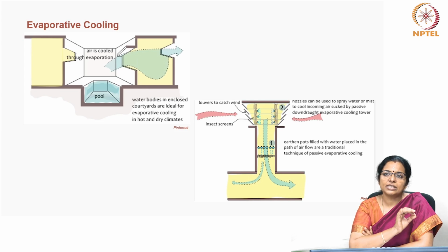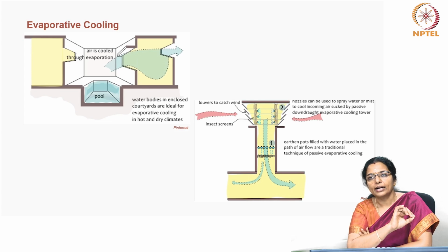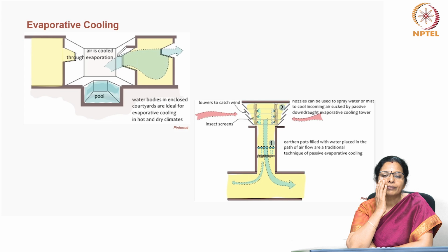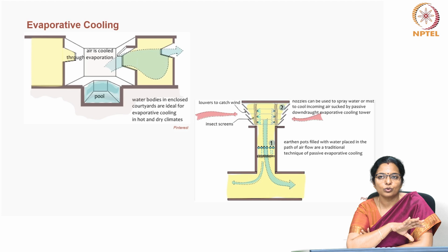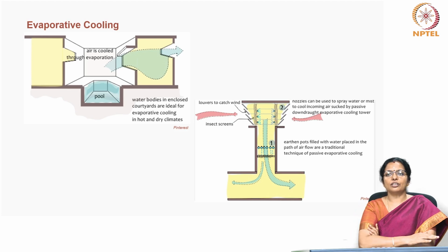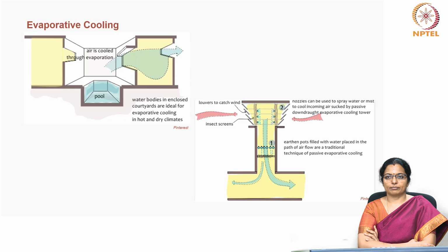A wind catcher is a traditional architectural feature which is used to capture and direct prevailing winds into a building, and it promotes natural ventilation and cooling. Typically, this is found in arid and hot climates where wind catchers are designed to channel airflow through the building, utilizing the pressure differences created by wind movement. These consist of openings positioned to intercept and funnel air currents, often leading to underground chambers or interior spaces where the airflow can be distributed.